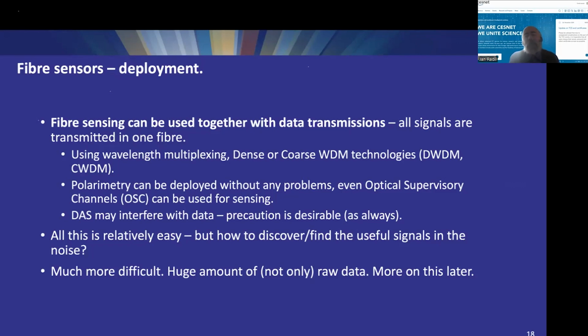DAS may interfere with your data because you are injecting something in your fiber, but it's definitely doable. I would say that everything I was talking about is relatively easy, but the biggest problem is how to discover and find the useful signal in all of the noise, because then we can try to be proactive and do something before the fiber is really cut. And this is much more difficult because a huge amount of data is produced, and more on this later.